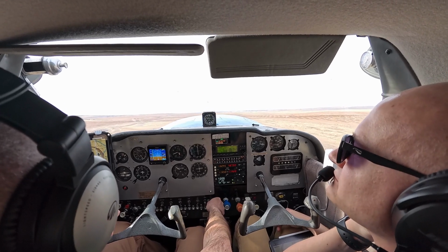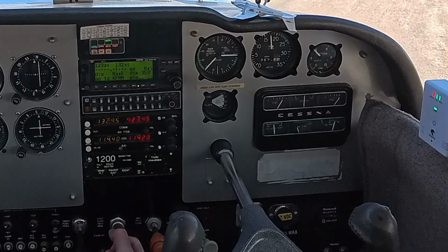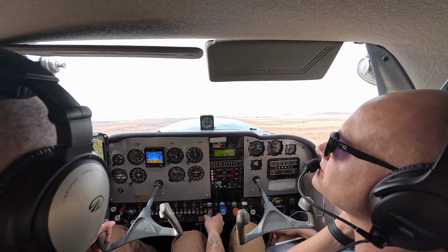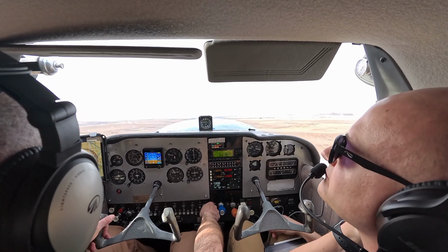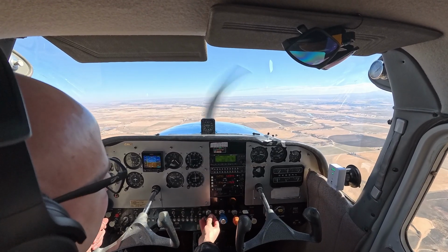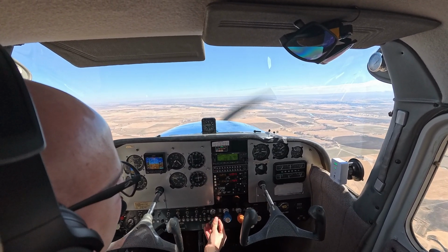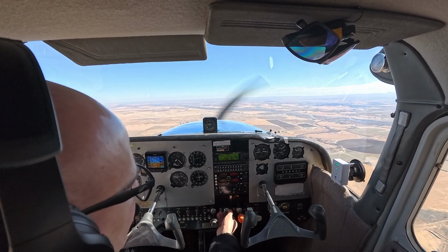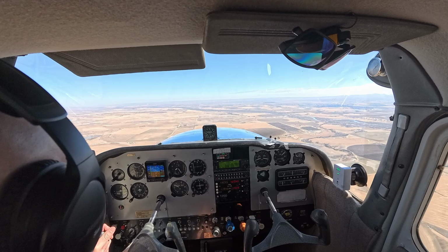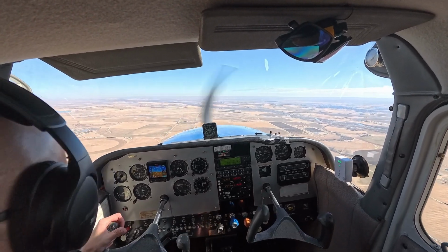In a high-performance setting, like takeoff and climb, the propeller knob is forward, making the blade considered to be in a low-pitch, high RPM setting. In cruise, we want to increase the efficiency of our propeller by pulling back on the propeller knob, which will increase the angle of attack of our propeller blades and decrease the RPM.